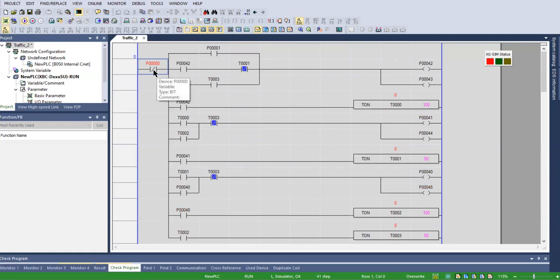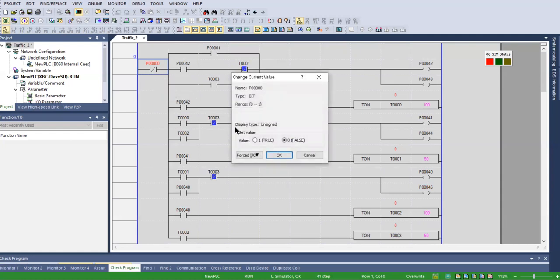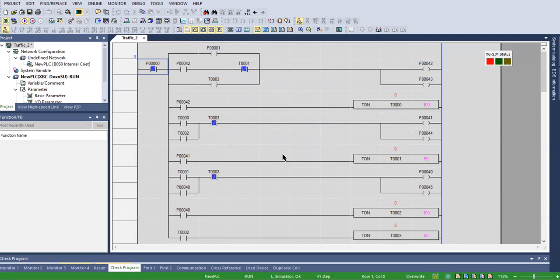So now if the port P00 stops receiving any input signal, it will go back to its initial position, the contact P00, which was in the normally closed state. But until and unless someone again starts the process by pressing the momentary switch at port P01, the system will not start operating again.